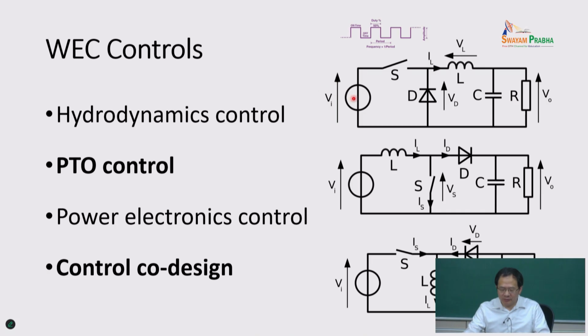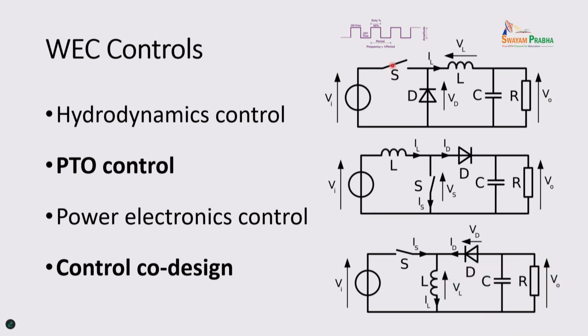And we talked about power electronics, right? And you have the wave generator. This is controlled by a step-down converter, step-up converter, or both, a buck converter, right? Here you use duty cycle to control the switch, when the switch is on and off, and you can charge and discharge this inductor.